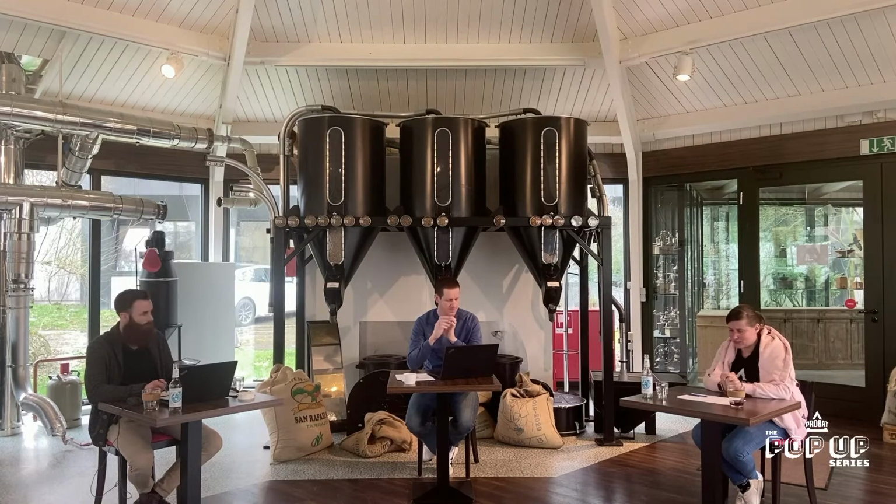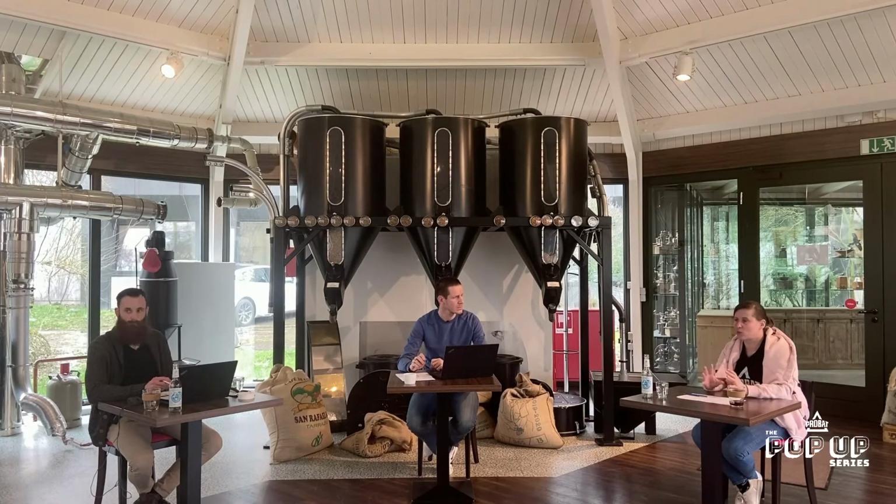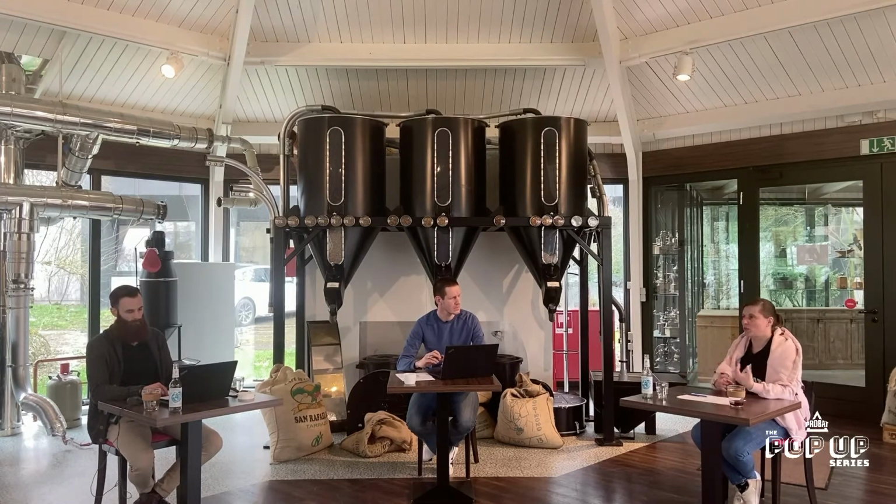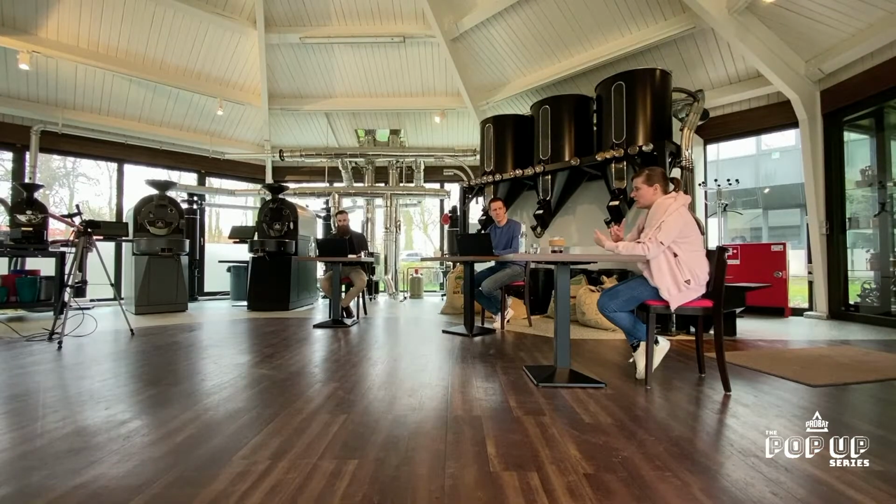Yeah, of course. A lot of people, what they do is when they like to roast small batches, they like to adjust the drum speed. But also here we need to look out how small is this small batch, and what will be the difference in terms of how will the beans be thrown through the hot air stream inside the machine. So also here the combination of airflow and also the combination of drum speed in terms of how is my burner set up. This is all being seen all together.